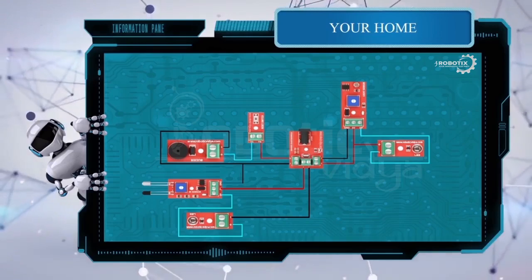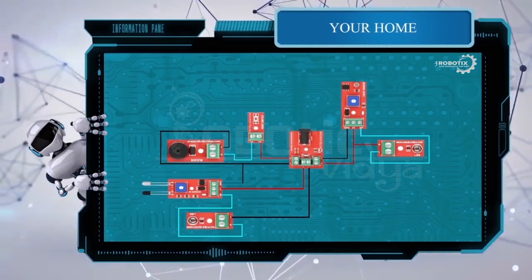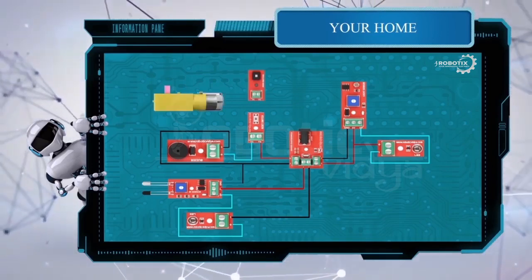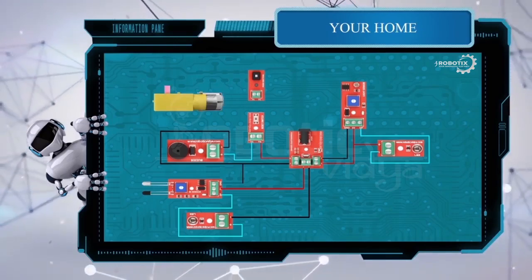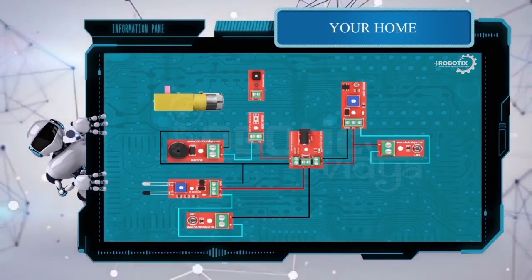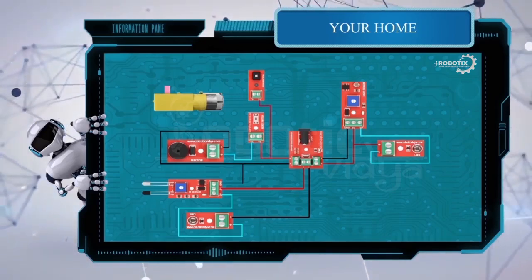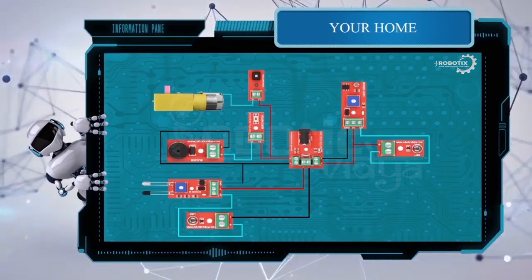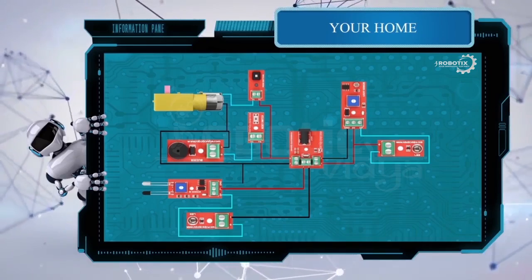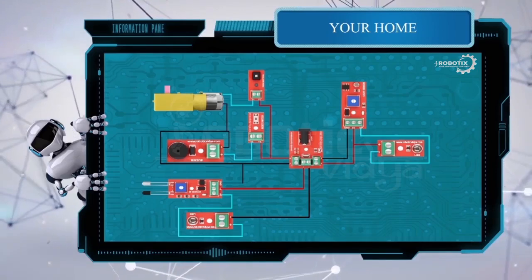The next one is your switch and fan. Now to control your motor using a switch, let's take your push button and your motor and screw it onto your project maker. Once done, I will tell you the connections. So now connect the plus of your power supply board to any terminal of your switch. The other terminal of your switch should go to any terminal of your motor, and the other terminal of the motor should go to the negative of your power supply board.